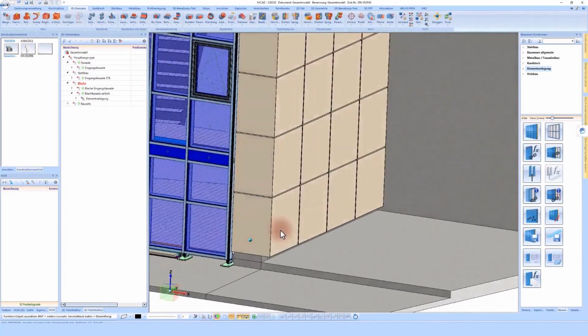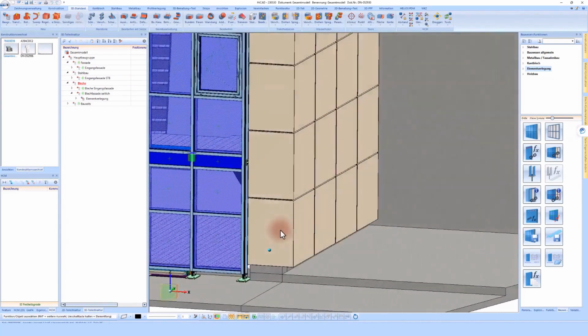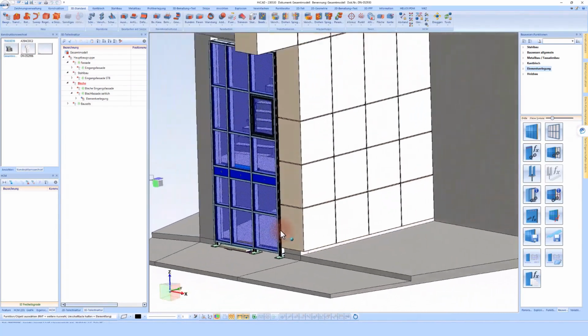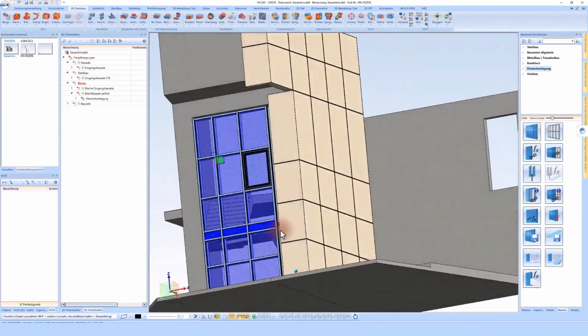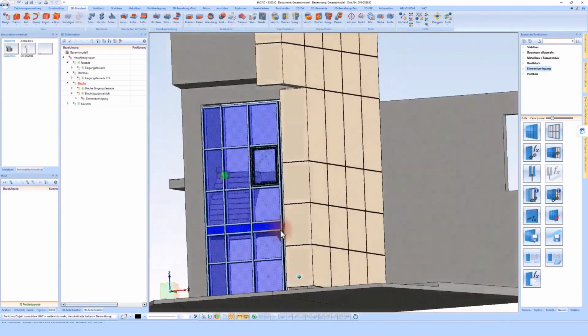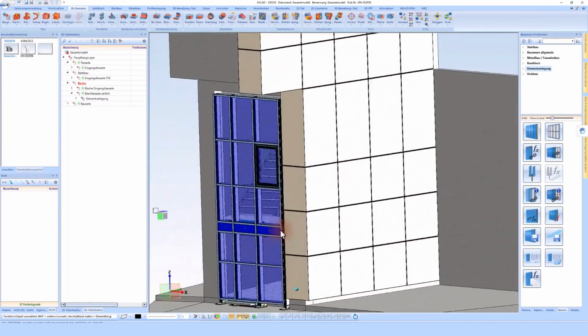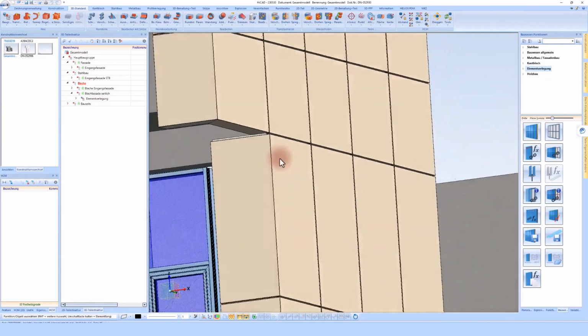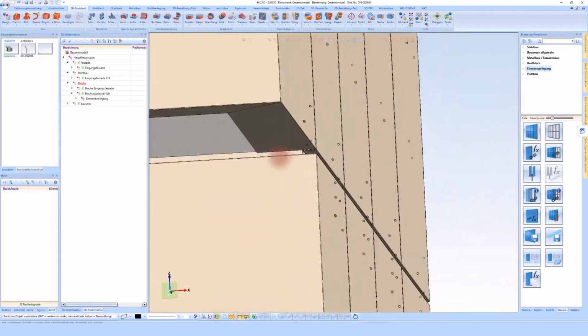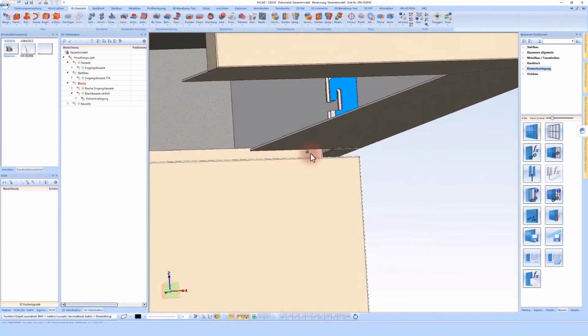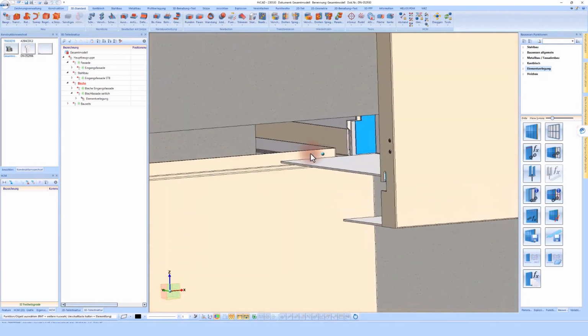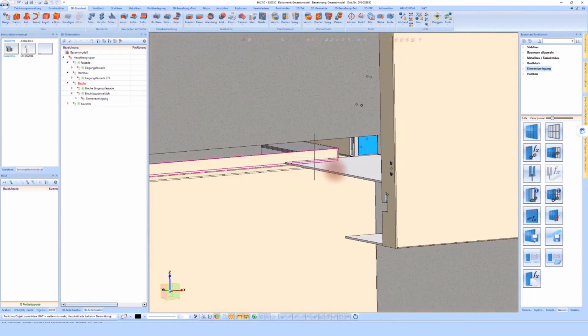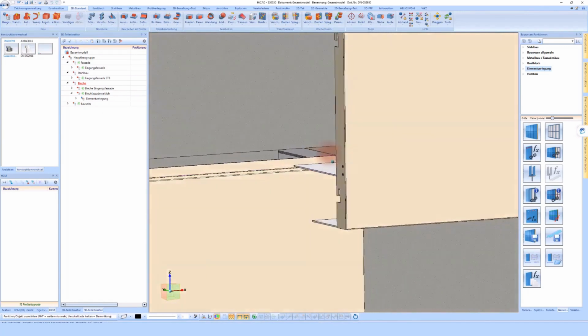As you can see, I have integrated my sheet facade here with the necessary corner points. There are certain corner points that still need to be further edited in this case, such as this transition here, which must be manually edited. Otherwise, I would encounter a collision.